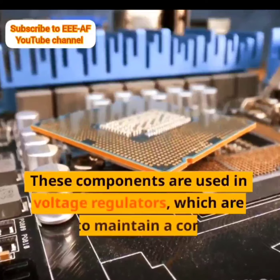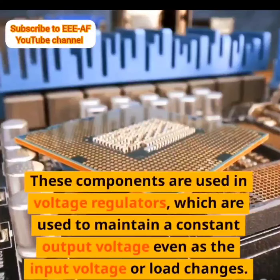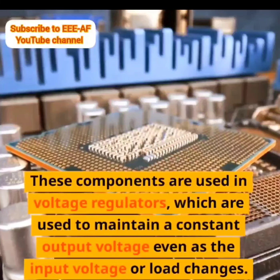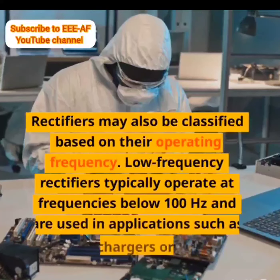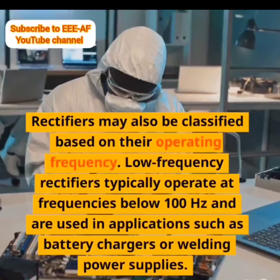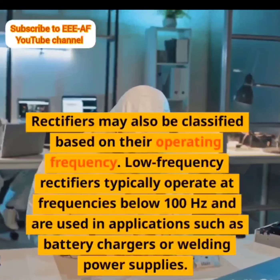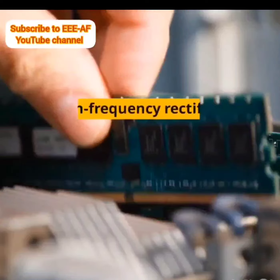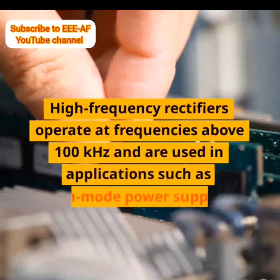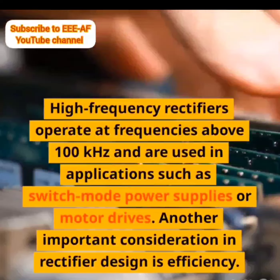These components are used in voltage regulators, which are used to maintain a constant output voltage even as the input voltage or load changes. Rectifiers may also be classified based on their operating frequency. Low-frequency rectifiers typically operate at frequencies below 100 Hz and are used in applications such as battery chargers or welding power supplies. High-frequency rectifiers operate at frequencies above 100 kHz and are used in applications such as switch-mode power supplies or motor drives.